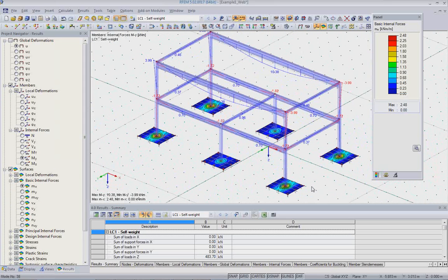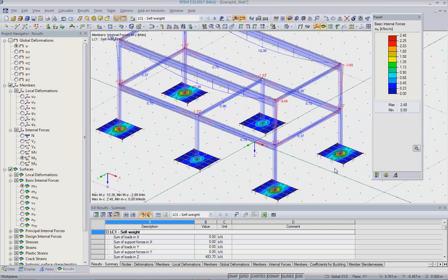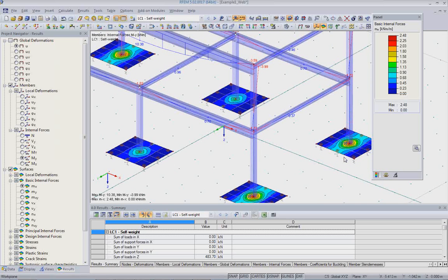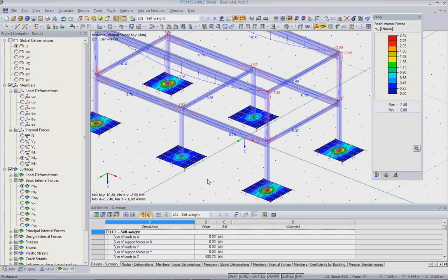It's clear also that it's maybe not such a good idea to model such situations like slabs, and there's a column with just maybe one node connected to a slab. We cause singularities.